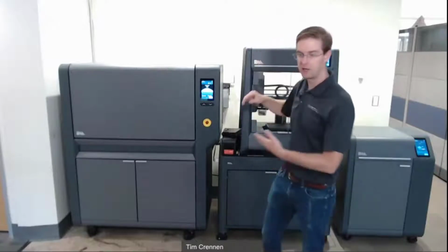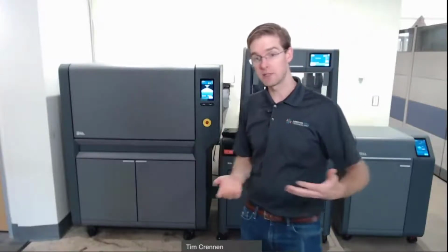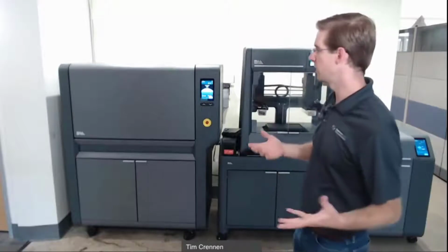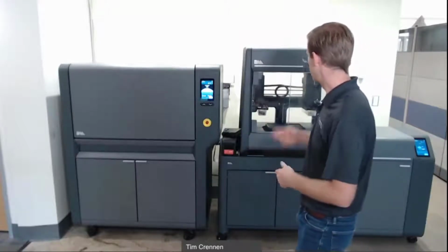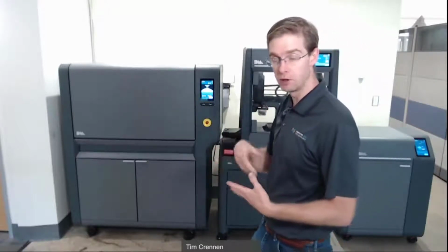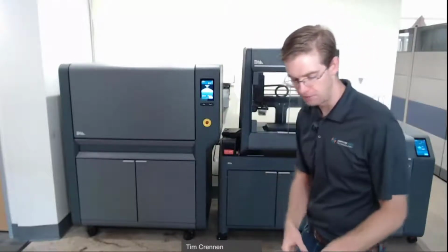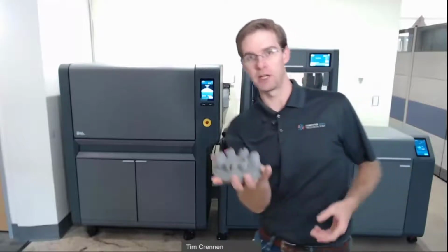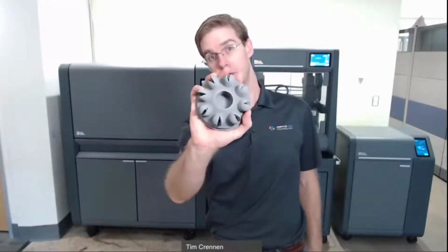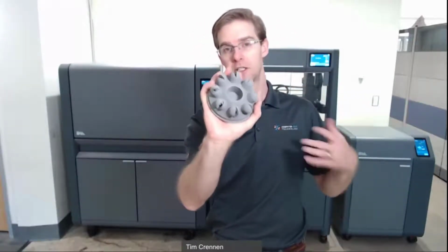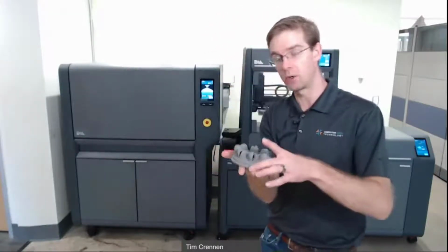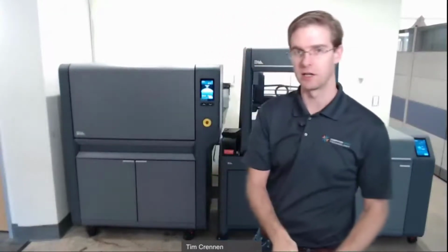Now we just hit print, and it works really similar to an FDM style machine, where it's actually heating up the tips and melting the polymers and binders in the rods, and not the metal, and actually just forming it into a general shape. And once it gets printed, we end up with a part like this. So this is just straight out of the printer, an uncured, soft part. It's kind of the consistency of a crayon. You can scratch it and dent it with your fingernail at this stage.